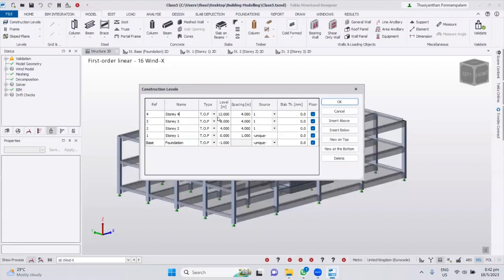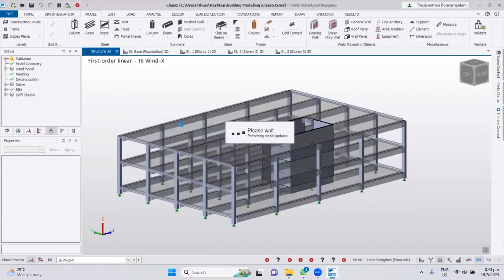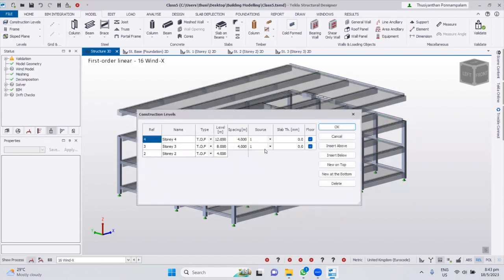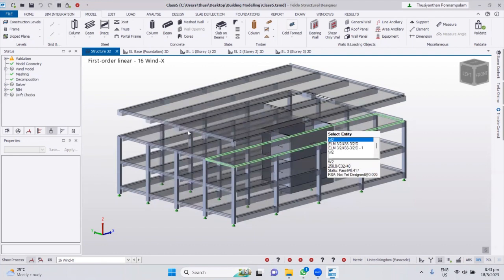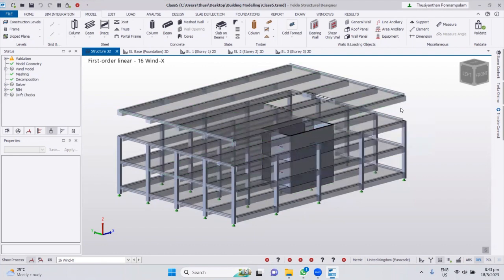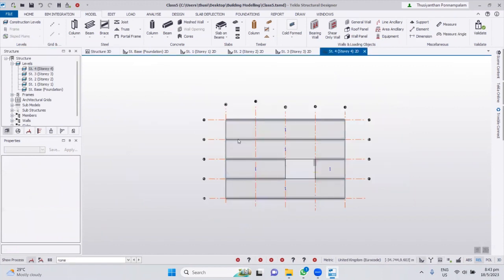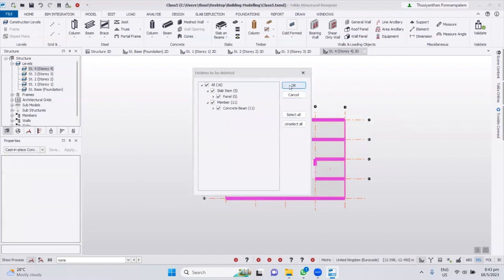Okay. So let's start. Story floor height, I keep it 4 meter. Then let's go to the modeling. Sorry, my mistake, I made it unique. It's not unique, right? Sorry, it's a unique floor, not a copy from the first story. So I go to level 4 and basically delete all of this. It was copied, so I delete everything.